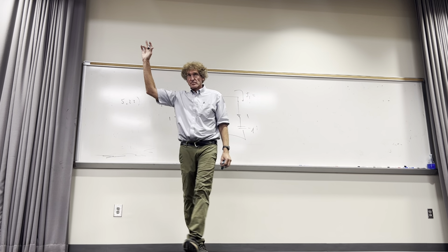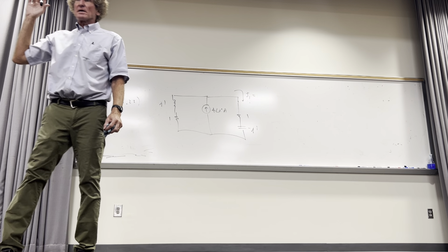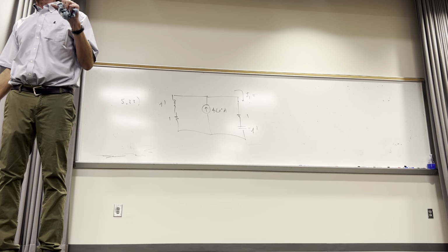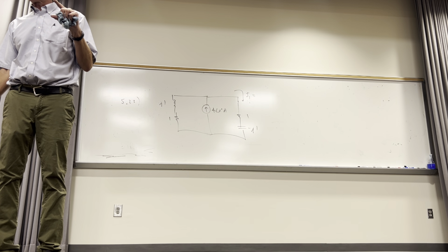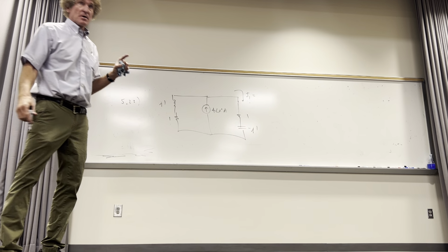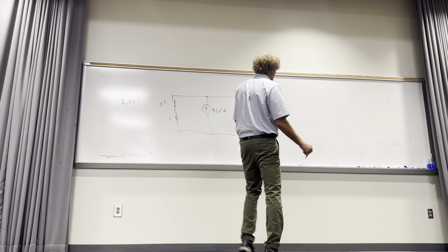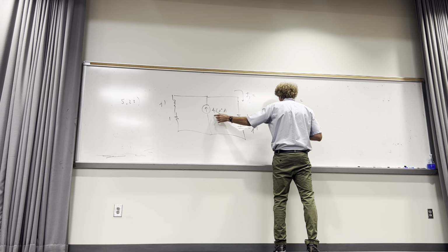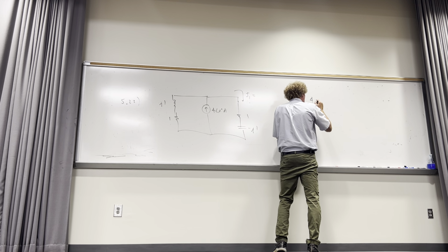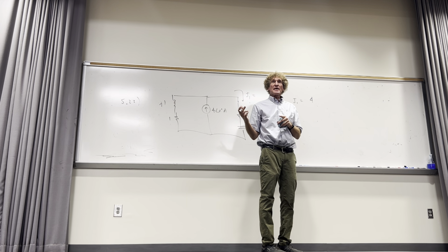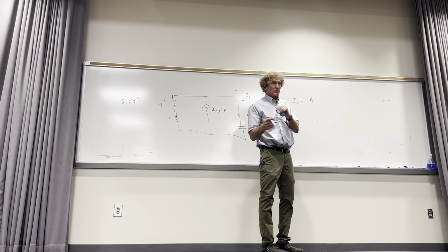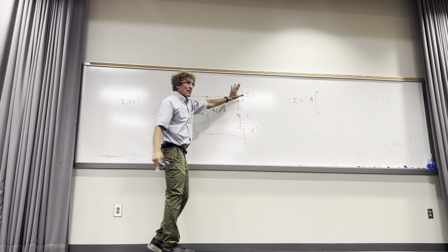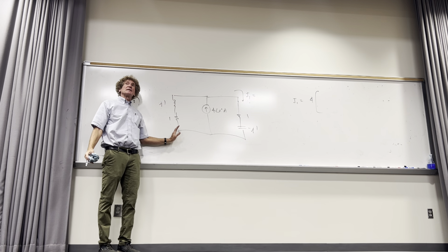Now, how many see this? What am I going to do next? I got the current that's going into both parallel terms of it, right? Both parallel parts. So what would I do to find the current I1? That would be the current going into both, which is 4 at an angle of 0 degrees. You don't need the 0 degrees. You all with me? Now what do I multiply it by? If I want the current here, I would multiply it by the opposite impedance, right?